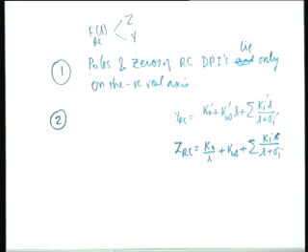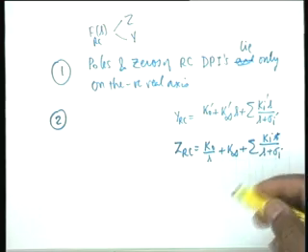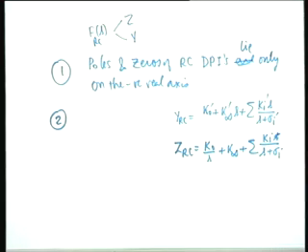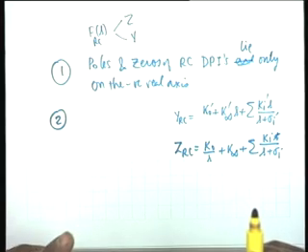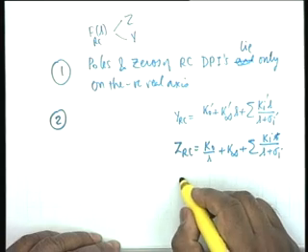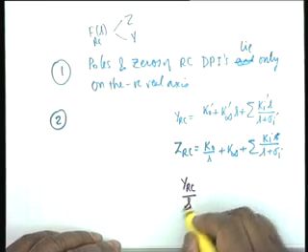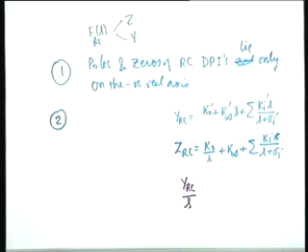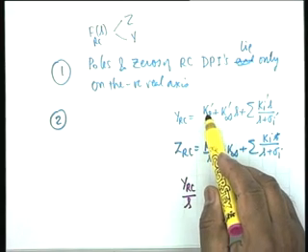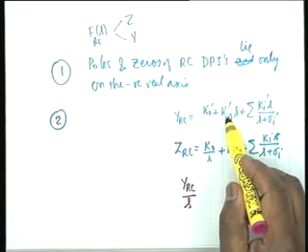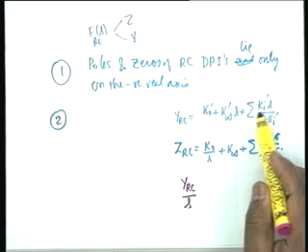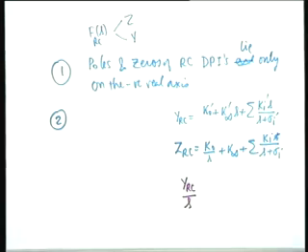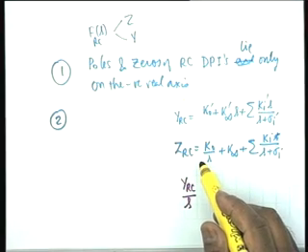Okay. I have written this again and again. Now, if I look at this, you notice that if I divide YRC by s, what are the terms that I get? I get K0 prime by s plus K infinity prime plus summation Ki prime by s plus sigma i prime, which is exactly the same form as ZRC.